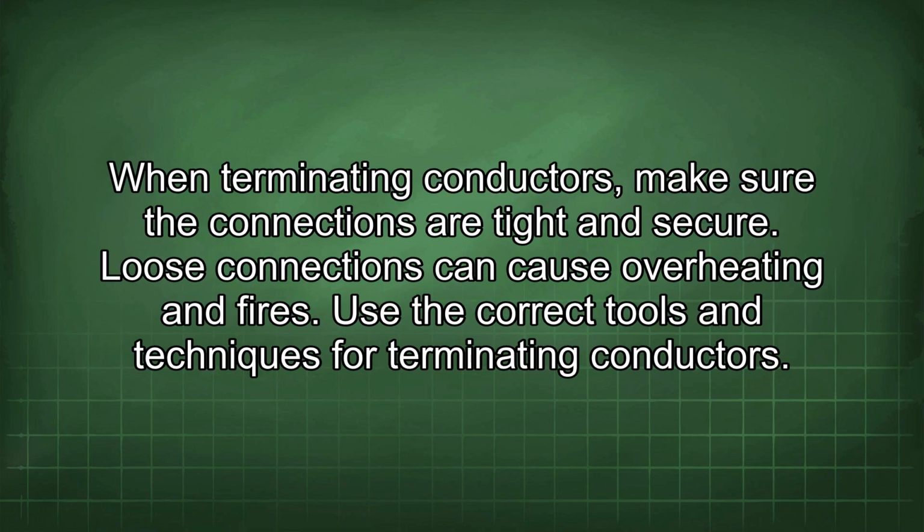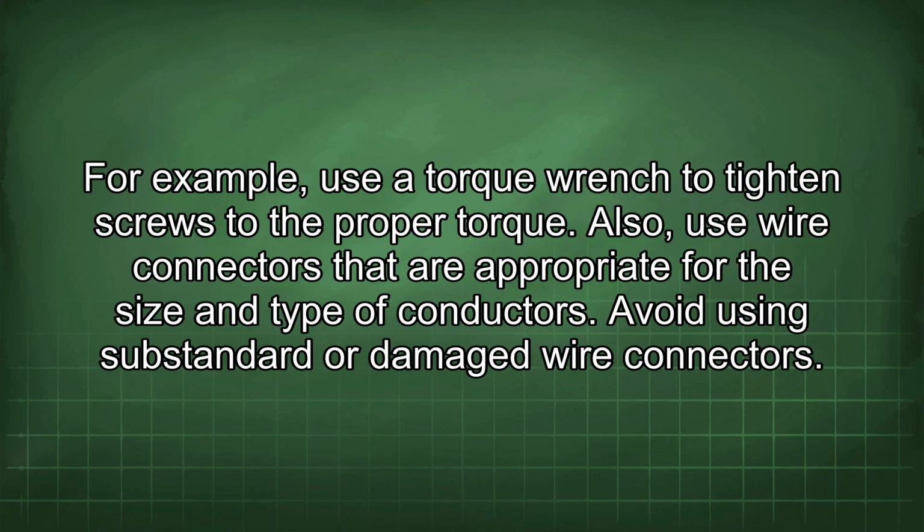When terminating conductors, make sure the connections are tight and secure. Loose connections can cause overheating and fires. Use the correct tools and techniques for terminating conductors. For example, use a torque wrench to tighten screws to the proper torque. Also, use wire connectors that are appropriate for the size and type of conductors. Avoid using substandard or damaged wire connectors.